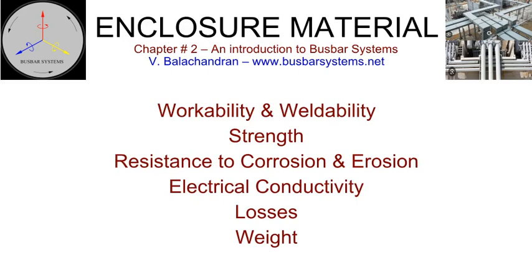Strength. The enclosures are expected to withstand internal forces generated by a short circuit and external forces caused by wind, snow, ice, vibrations, and seismic activity. Resistance to corrosion and erosion. Enclosures are subjected to corrosion and erosion depending upon the service conditions. Surface coats provide additional protection and enhance life. Gas-insulated bus with aluminium enclosure may be buried below ground. Apart from providing surface protection with coats, sacrificial anodes and cathodic protection are provided to counter the effect of corrosion.